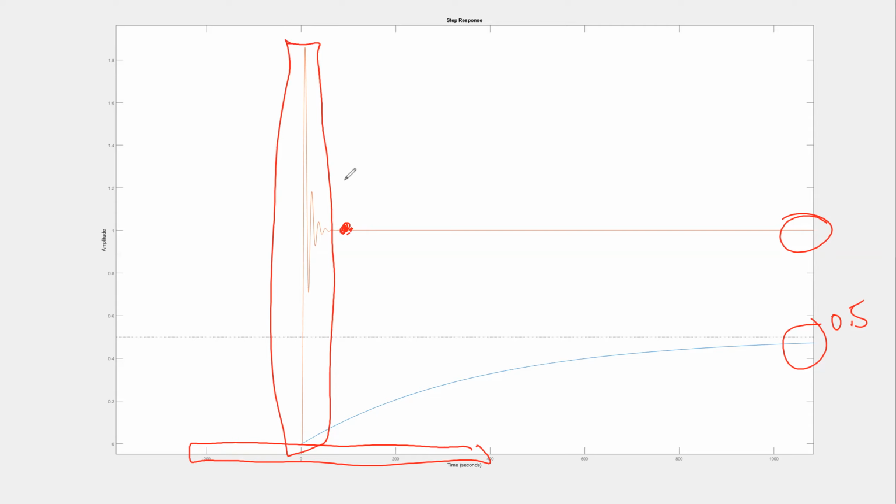So, you know, if we didn't like that much overshoot, we could reduce the gains. We would still get a decent response. And we also still have the added benefit that we have eliminated the steady state error with the I term. So these tuning rules give you a starting point based on what they've been designed to do, which is give that quarter amplitude decay response. But from there, you can tweak the values.